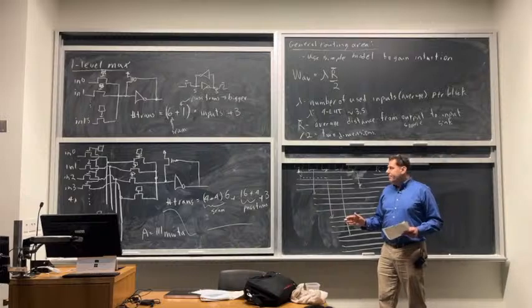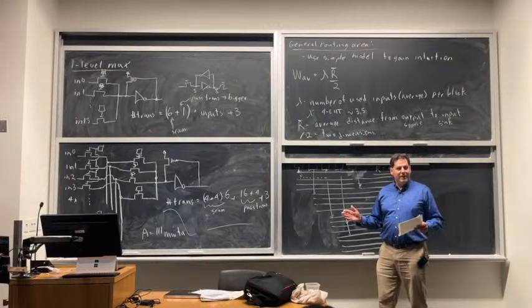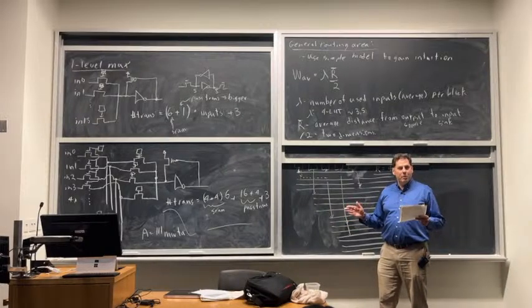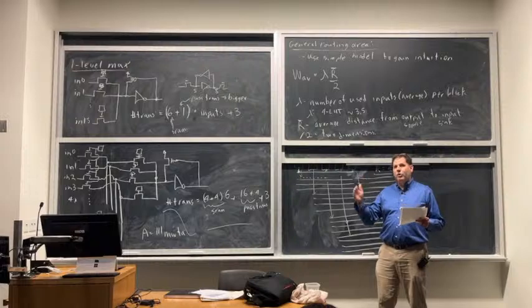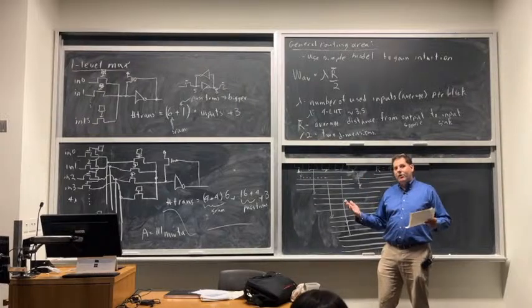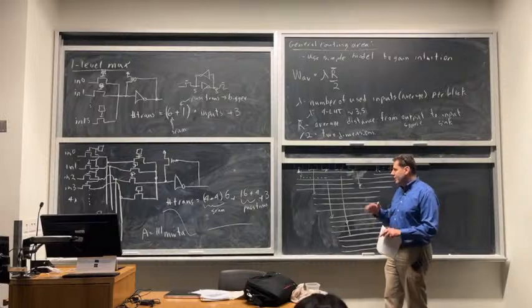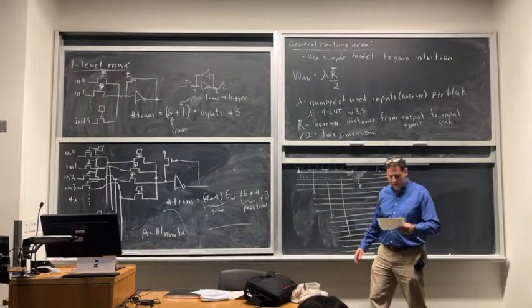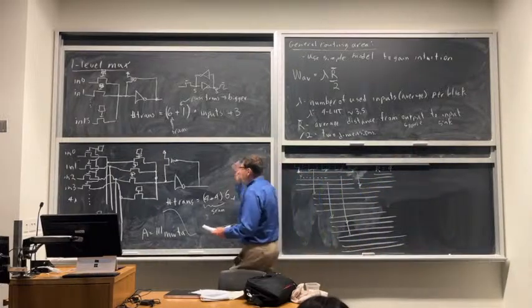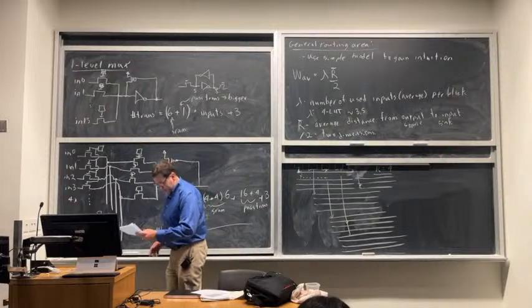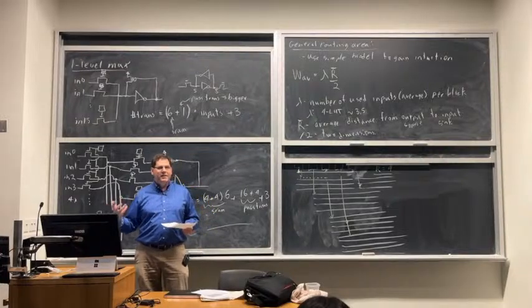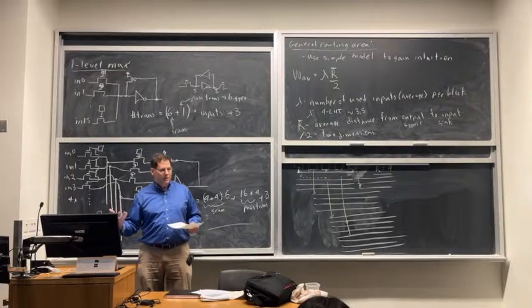It's certainly not very often, right? So if you did that once in your chip, maybe it would work. If you did it in every single location, like the 10,000 locations in your chip where you have routing channels beside blocks, there's no chance it's going to work. So this gave us the average routing channel. We actually need to find essentially the peak, okay? That's what we really need to build. We need to build a routing channel that has some extra margin.